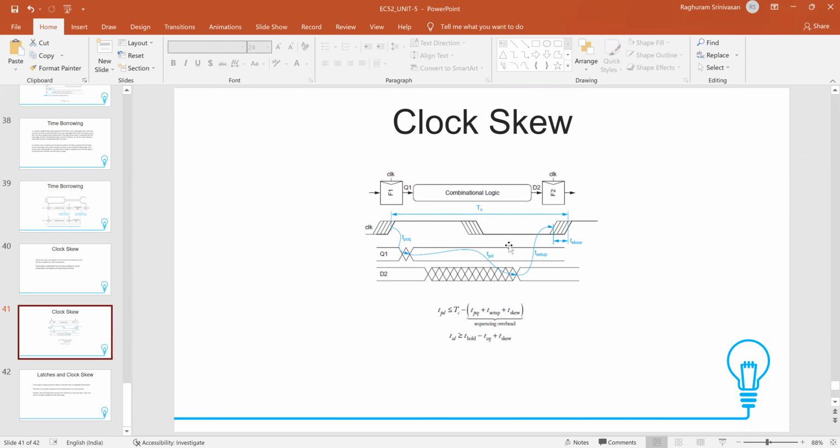So if you see the propagation delay problem, the maximum amount of propagation delay has reduced because the next clock cycle might come earlier, which means that the amount of time required for the logic block is even smaller. So your propagation delay has suffered because of the clock skew. Originally, if say your maximum propagation delay for your block was 50 nanoseconds, and the clock skew is 5 nanoseconds, that means that in 45 nanoseconds itself, your output should be ready. You don't have the full 50 nanoseconds.